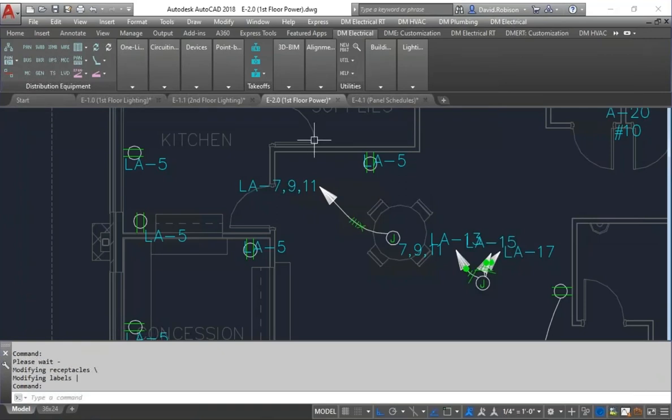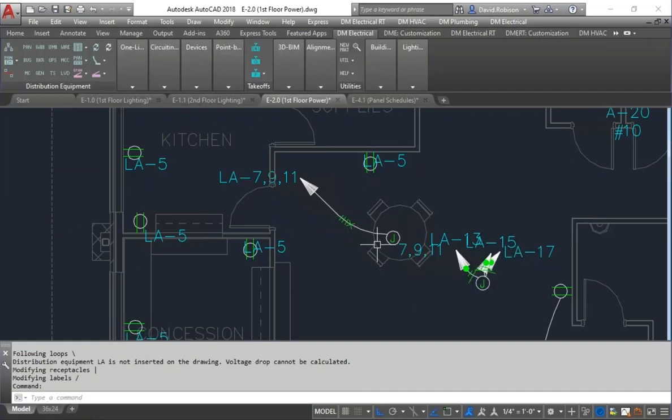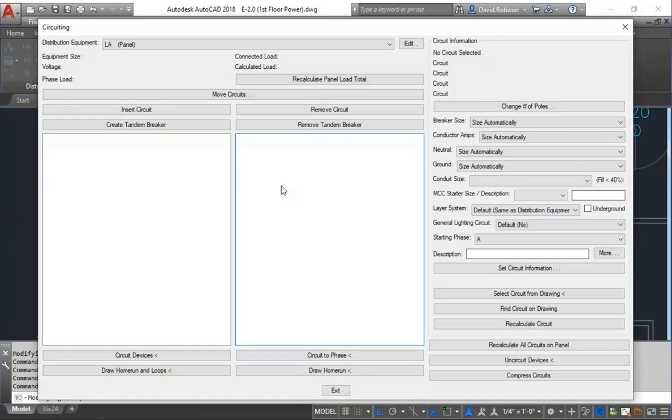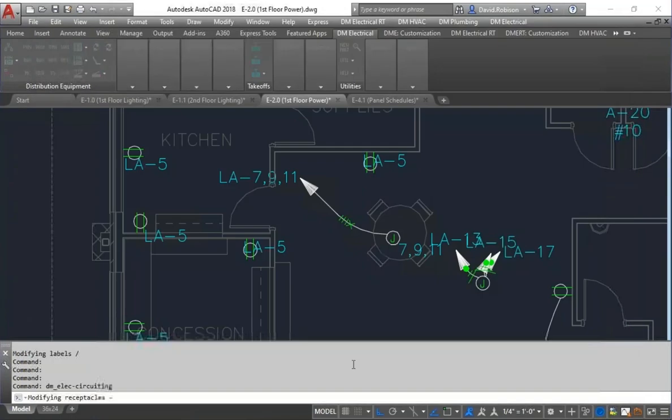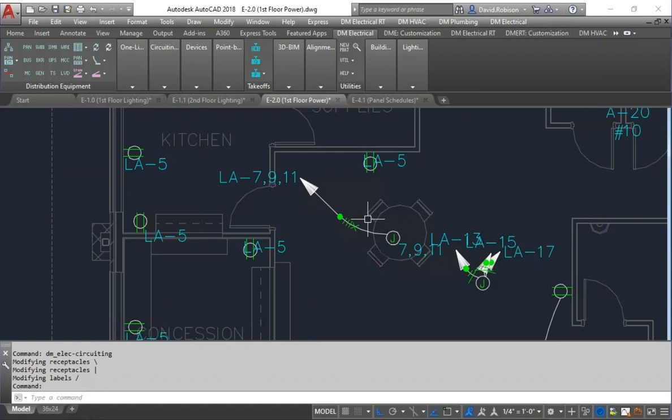Someone is also prompting that you can go into the wire customization and make a different wire size there as well. So there are lots of different ways you can do this. Now there's no ground wire there. You have to redraw the home run. Actually, it depends. You actually don't have to. In this case, it didn't. If I come here and put the ground wire back on, it updates automatically. If you're changing the blocks themselves, do you need to redraw them or run a coordinate drawing in database to get a chance to update things?